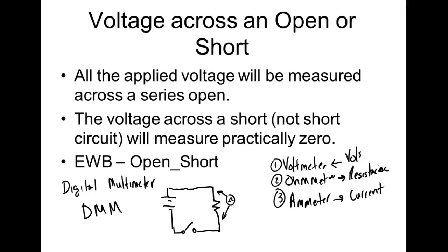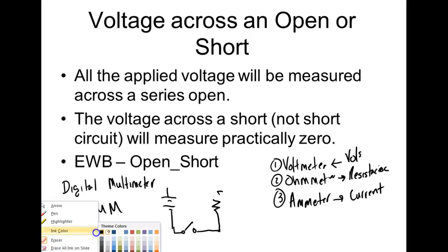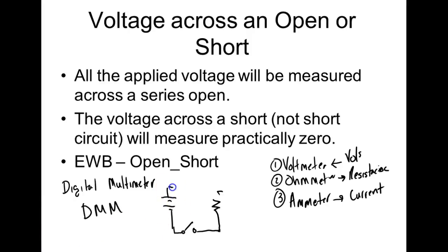Oh, there it is. The problem with an ammeter is we got to make the current flow through the meter. So what we have to do is we open the circuit, we make sure power is turned off the circuit. Then what we literally do is we come over here and we open the circuit. Then what we do is we come over here, we make sure amps are selected, and then we put the meter in line, or what we call series, with the load.